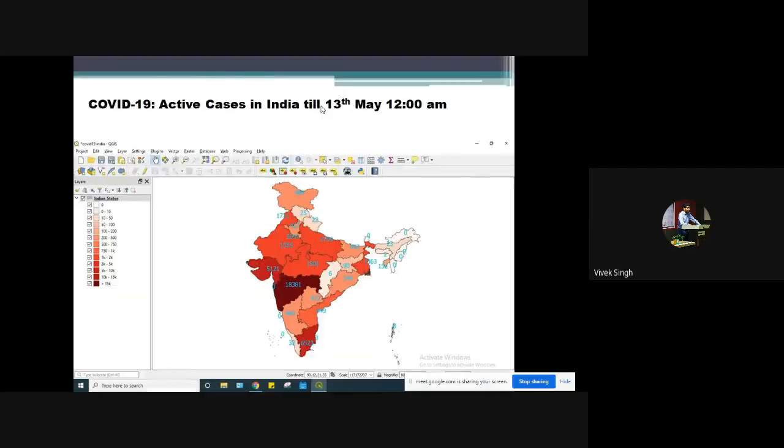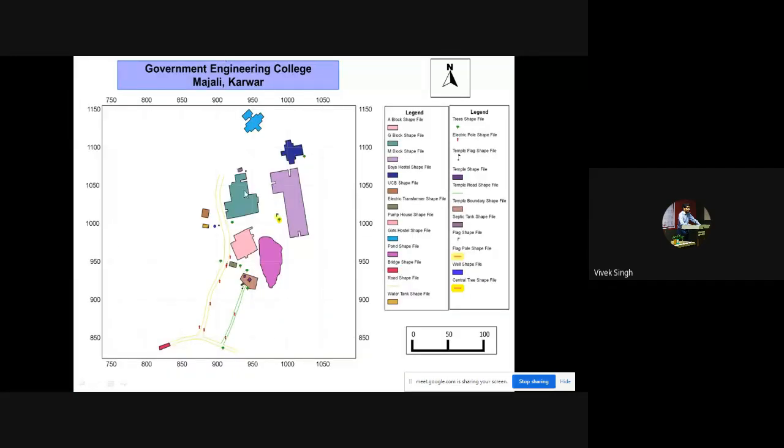So what we did was, all the students and me as well, this was the college, you can see. We took the coordinates of all the important points in that college. As you can see, this is a map of that college. So using Total Station, we took all the points, all the building points, pond. You can see this is a pond, this is a tree, this is a flagpole, these are some shops, there's a temple as well, these are the roads. We took road points, tree points, there was a bridge as well, and there was a beach after a few kilometers. On this side there was a beach, but we didn't go till that point. We ended the whole survey here.